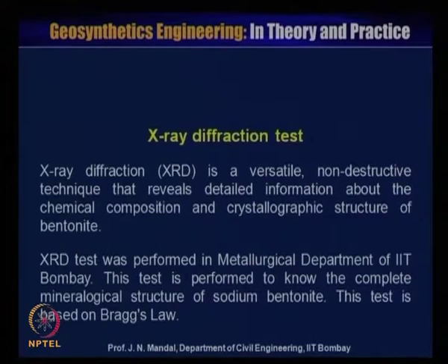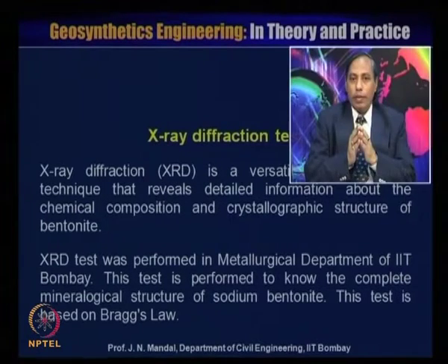Next, the X-ray diffraction test. X-ray diffraction is a versatile non-destructive technique that reveals detailed information about the chemical composition and crystallographic structure of bentonite. The XRD test was performed in the metallurgy department of IIT Bombay. This test is performed to know the complete mineralogical structure of sodium bentonite. The test is based on Bragg's law.